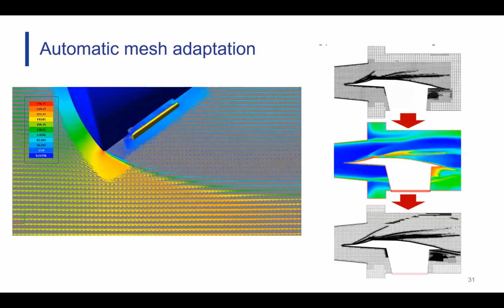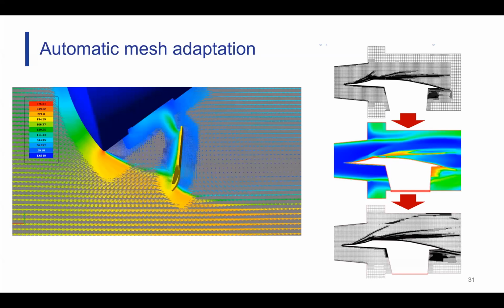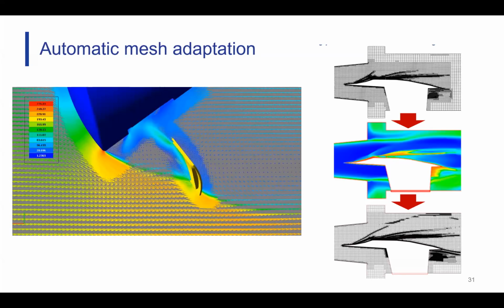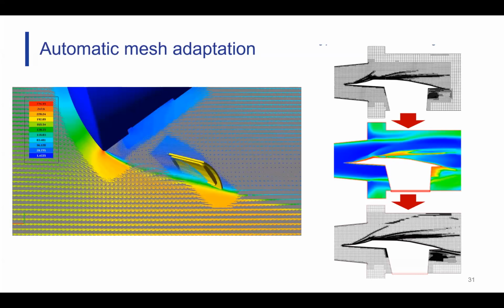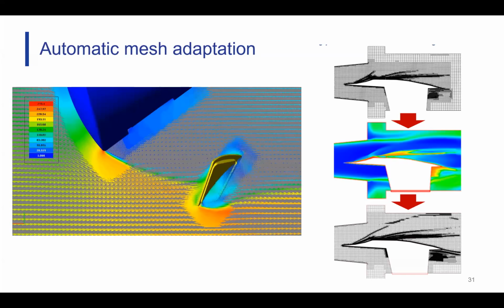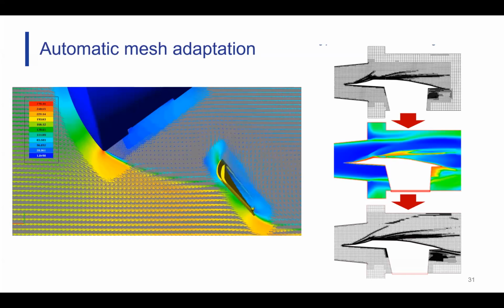Automatic mesh adaptation. Now this is actually really cool. So again, we have moving bodies. We don't know beforehand how our solution is going to look. And we know that mesh refinement can be assigned to regions around objects, or maybe to occur by condition. What this means is that the mesh will dynamically change throughout the simulation. Here in this visual example, we have a lid detaching from some manner of airborne capsule. Do you see how the refinement follows the object?